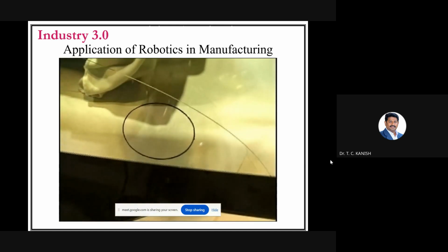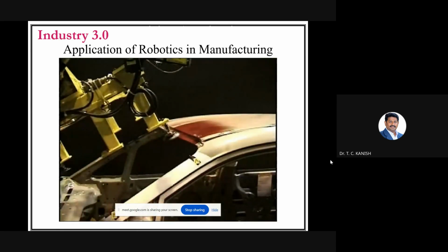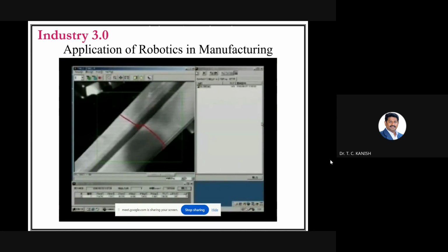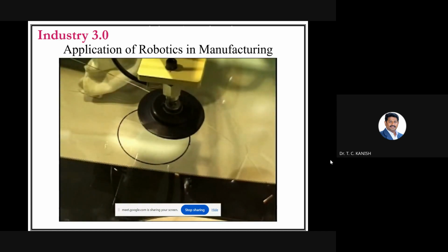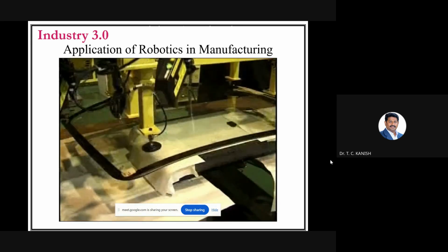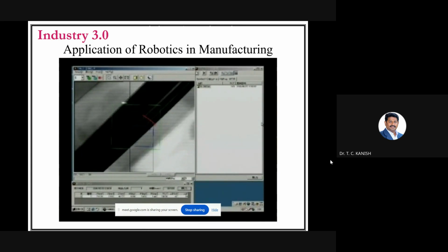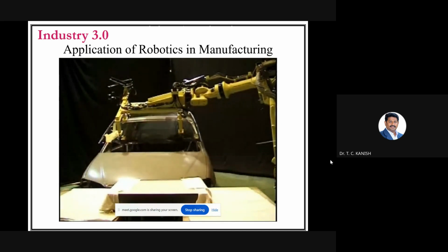So this adjustment, the first round, they made manually. So now it is going and measuring. Once it is measured, it identifies where the exact location is. So once it is found at the location, it will come back again. You can see the error, whatever the circle is made and whatever the gap it holds. So that's the error it found and now it is fixed exactly to that. So that means it auto corrects whatever the error is, and it will keep it.